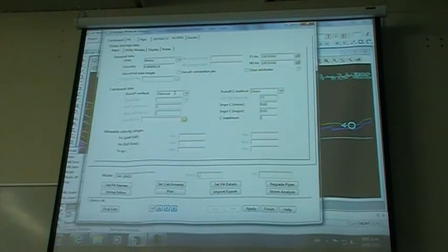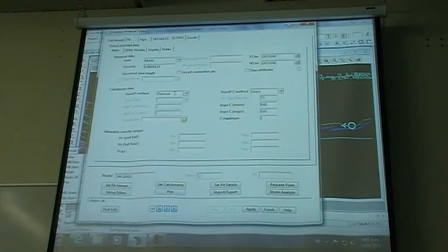Has anyone else got a warning under pit type? All it means is that the default setting under the drainage defaults that is in there will be concrete cover as a default. It's not in the drainage.4d file, so it's asking you to update it to a pit type that is. So if you just go into, say, a manhole 1050 or something like that. Okay, so all it's saying is it can't find that in its default list.